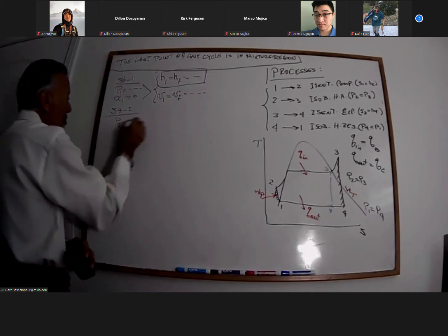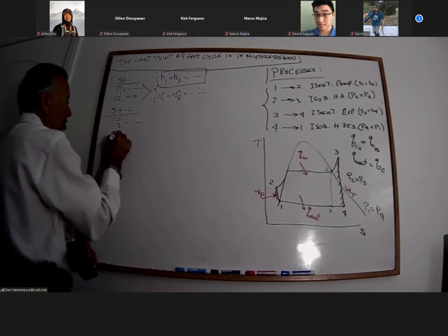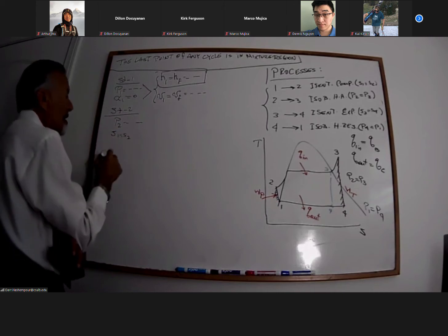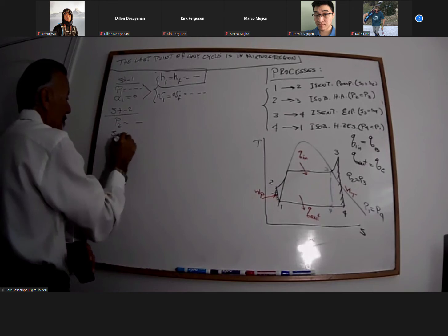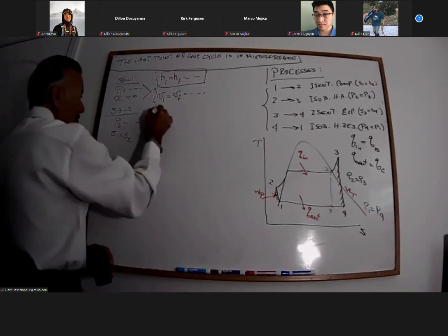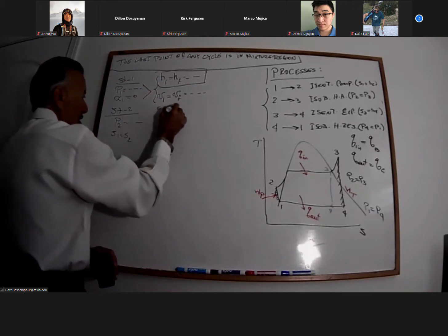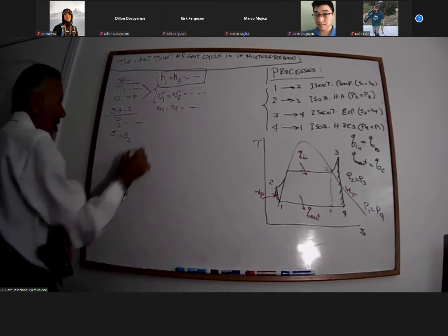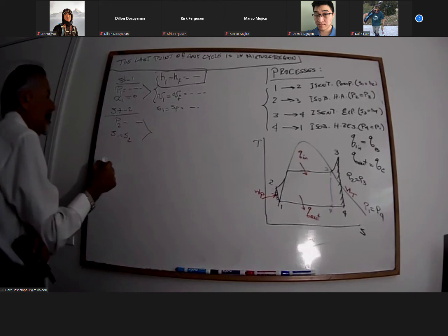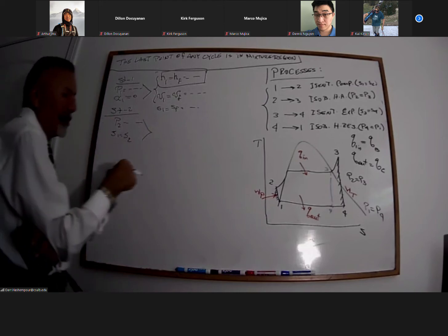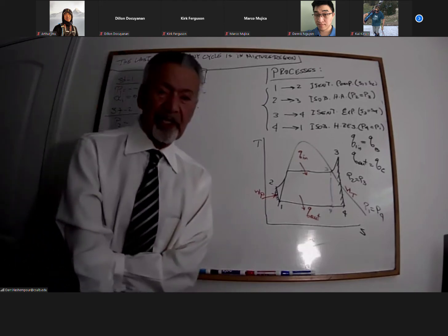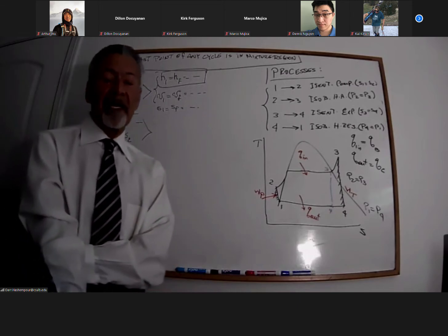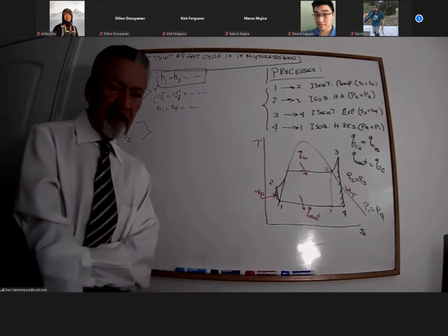Using P2 and S1 being equal to S2, that means I have to find S1, which is S of F, in the first place. Then, based on these 2 values, and based on interpolation, I find the H2 value. That is a painful process.